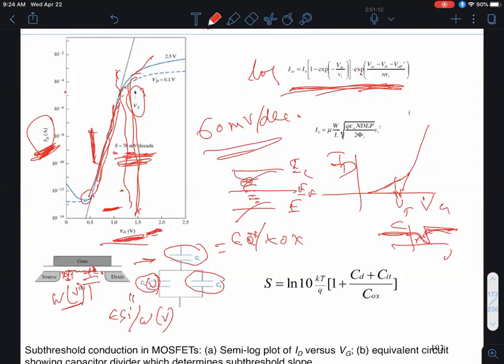When the bands unbend, the same states, if they move above the Fermi level, will not be occupied by electrons. Anything that results in some sort of charge storage is tantamount to capacitance, and that's what this capacitance is. It's called the interface state capacitance, which, if you look at the structure, is in parallel with this.